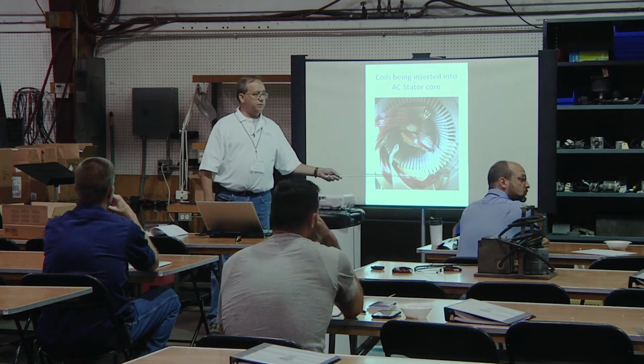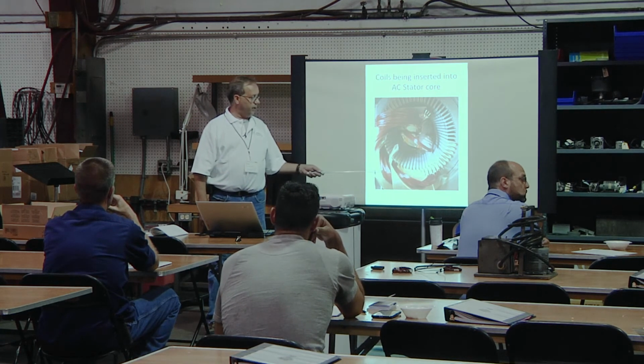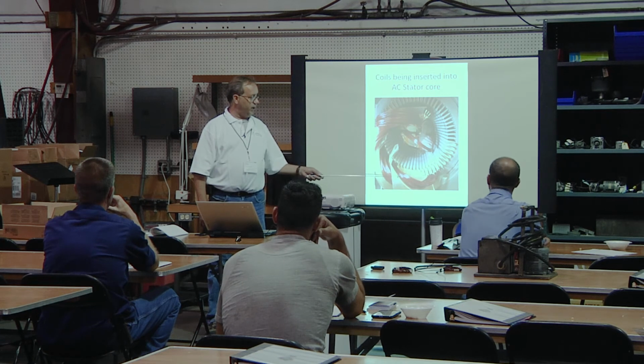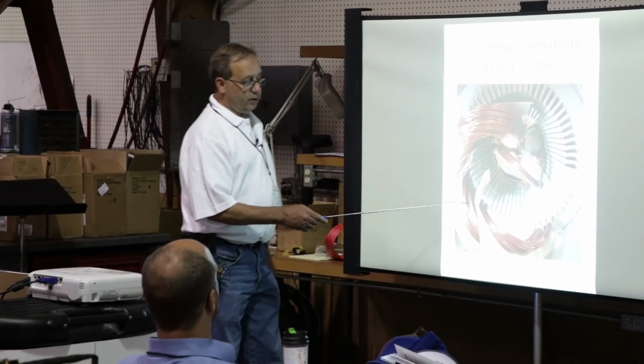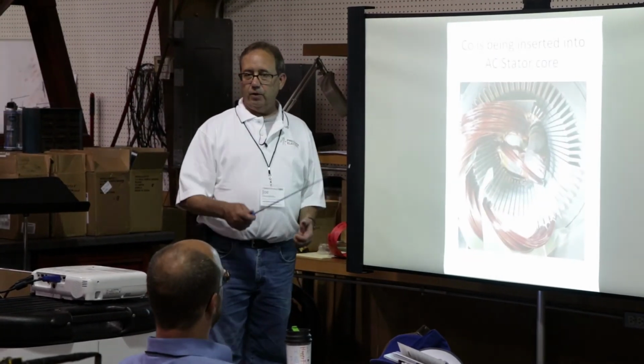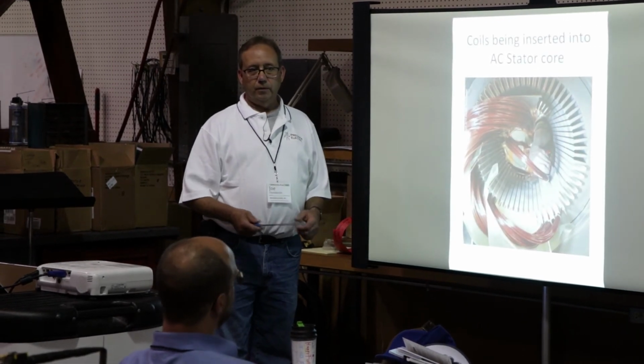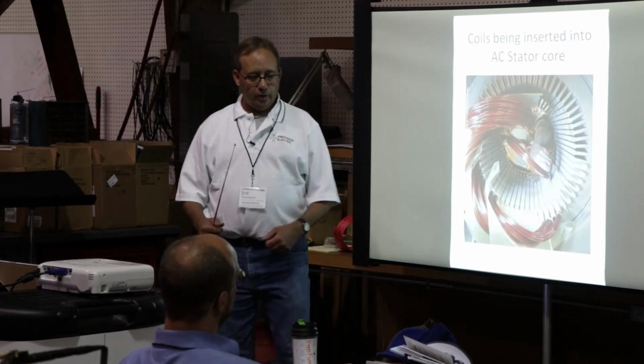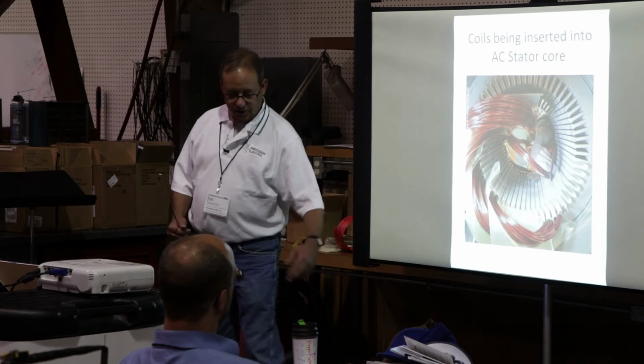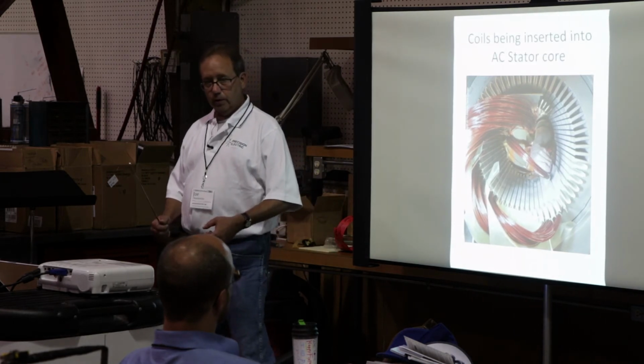Each one of these, this phase paper that goes in between here, that's separating A phase from B phase. This one is physically put in the opposite direction. If they make a full group, they might put one on straight. It's still connected to the next group.